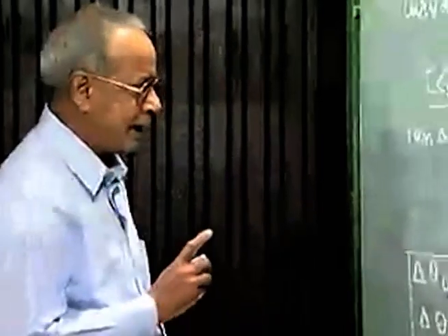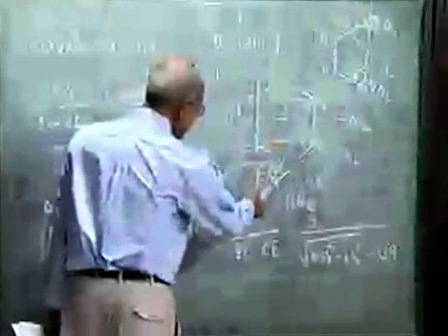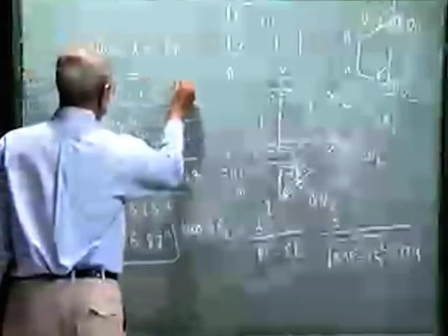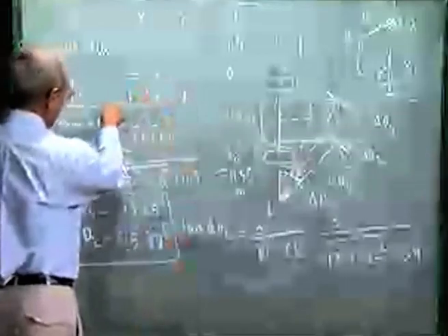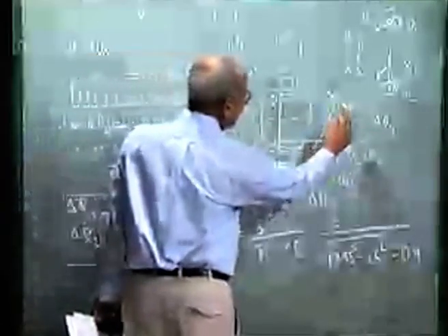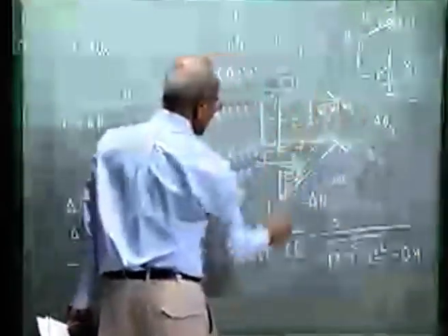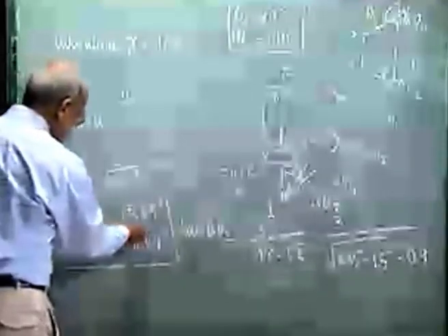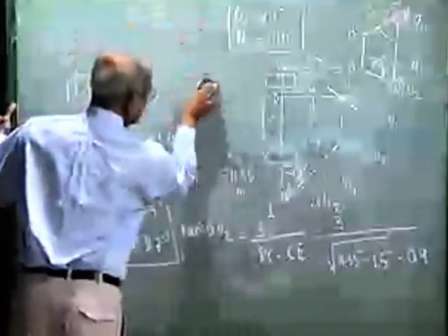So we see that if we want to satisfy the perfect steering condition corresponding to the radius of curvature of this point G of 11.55 meter, that is a little higher than the minimum value of 10 meters, this is our accuracy point where the steering condition will be perfectly satisfied. These two wheels from the neutral position will rotate by delta theta 2 and delta theta 4, which are given by 15.87 and 13.65 degrees. So we get a second pair of coordinated values for theta 2 and theta 4.